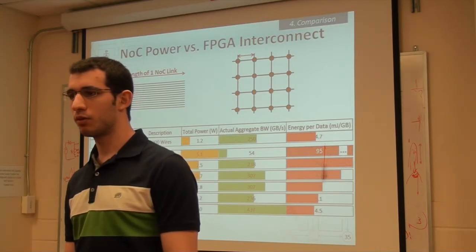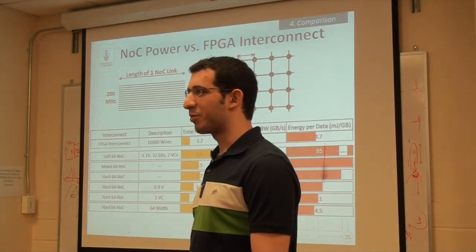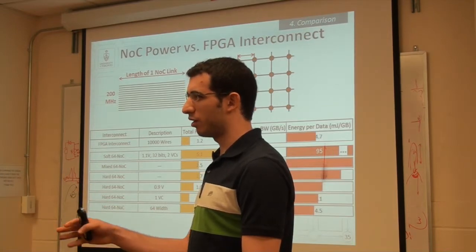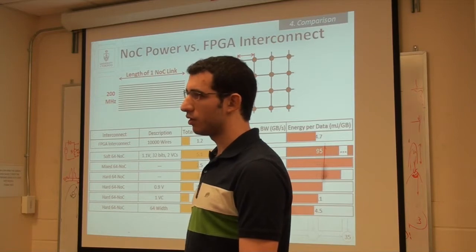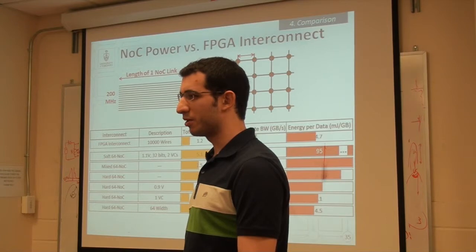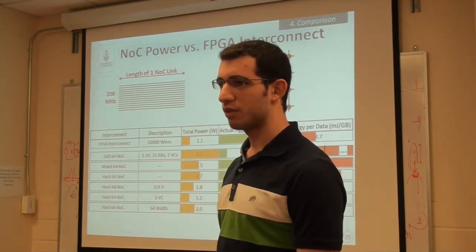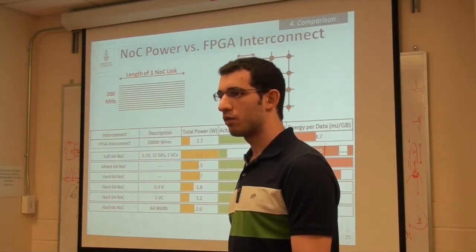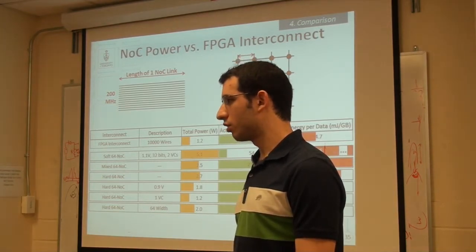When you basically have your high priority, you're not blocked. Okay. I have to remember the number again now, but it was close to what we got with QSys. So QSys, because we added like 3 pipeline stages, and on the NOC. Well, let me bring up the number. It's in that last paper. So it was very close. It was like 10.5 nanoseconds to go across one router. No, that was actually for the average between the near and the far.